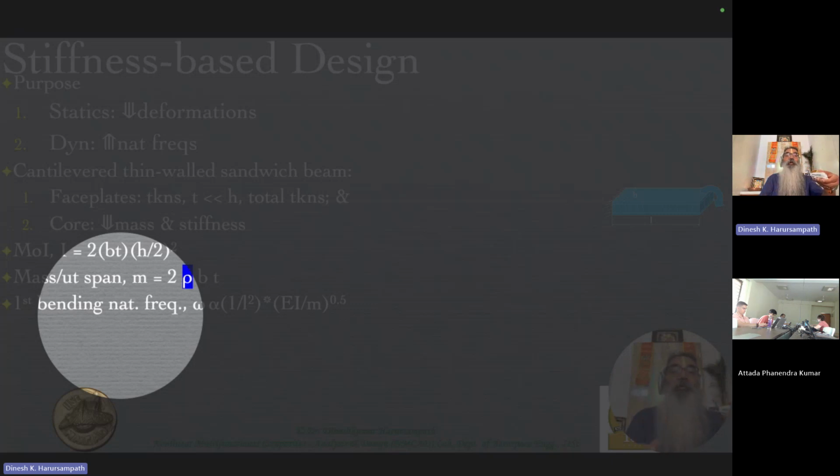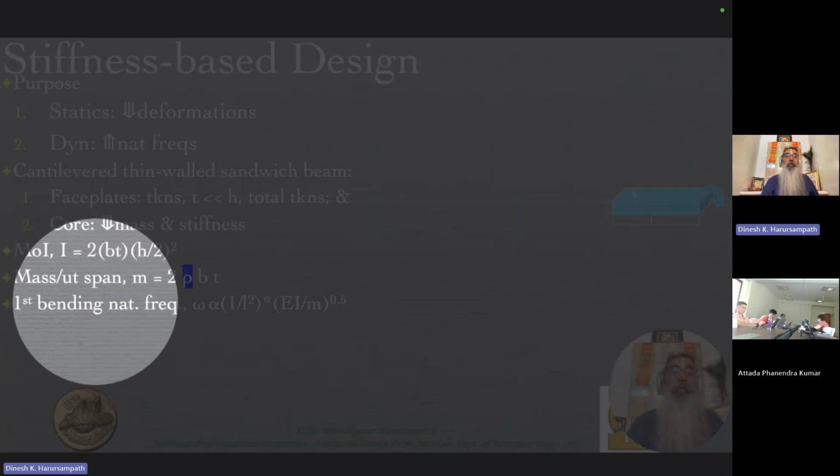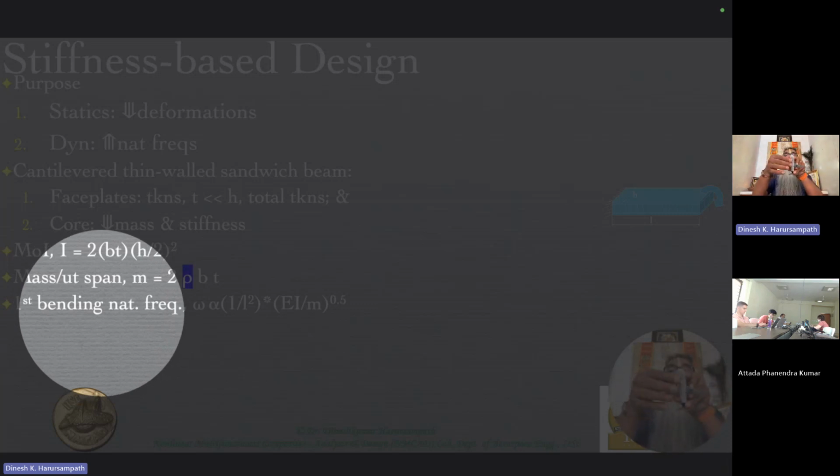But just to qualify each of them, we need to make sure not only by the number, say first, second, third, etc., but also say what is the mode shape if it is uncoupled. There are some coupled natural frequencies as well. So, in other words, the bending alone may not be happening by itself. Bending and torsion might be happening simultaneously with the same period. And so, therefore, there could be a coupled natural frequency associated with that of flexural bending with a torsional, flexural-torsional kind of a mode shape that you could have, for which there could be a natural frequency.